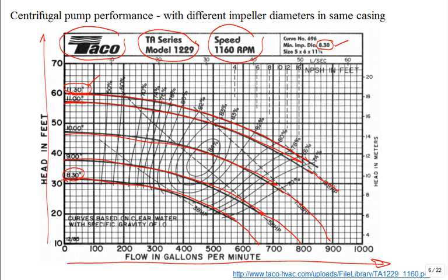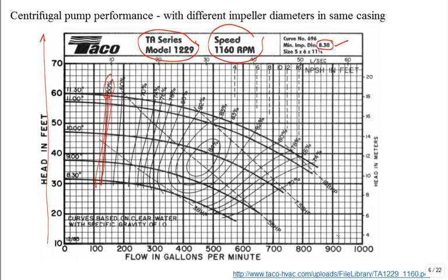Don't operate in those vicinities. Just don't even think of it. They typically extrapolate these curves beyond, say, 50% efficiency just because they want to give you numbers to tell you how big the impeller is and maybe the deadhead pressure, the cutoff head. But otherwise, don't even try to operate out in here, and do not operate out in there, okay?